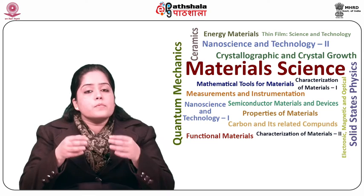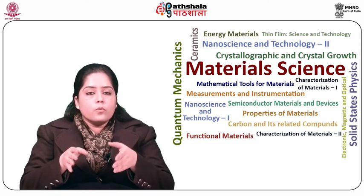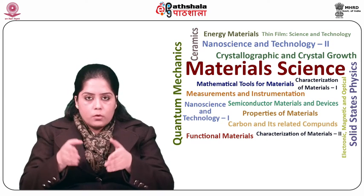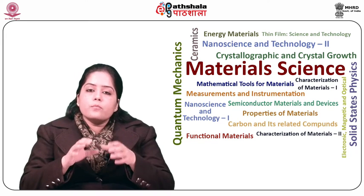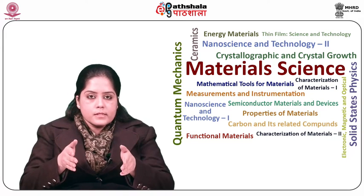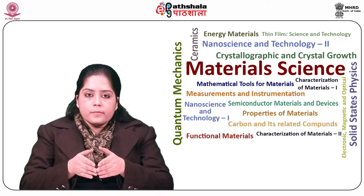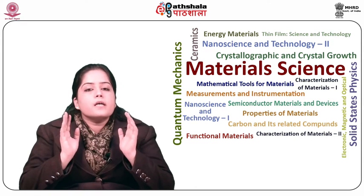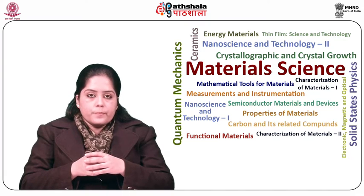Next, SRAM cells consist of 4 enhancement mode MOSFETs and 2 depletion mode MOSFETs, the 6T cell. The depletion mode MOSFETs can be replaced by resistors formed in undoped polysilicon to minimize power consumption and give high packing density, the 4T cell.